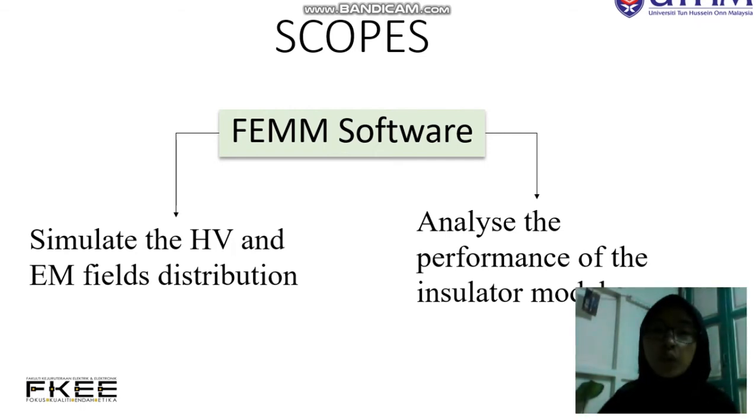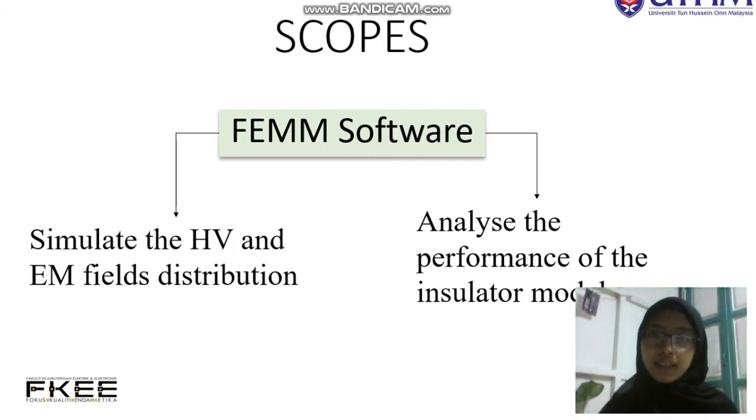Once we come out with the design of the insulator based on many aspects that we need to consider, the material, the size, the diameter, we use FEMM software to firstly simulate the HV and EM field distribution. And then the second one is we use this software to analyze the performance of the insulator model.